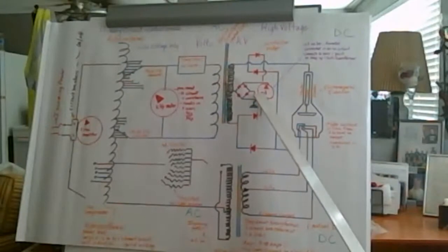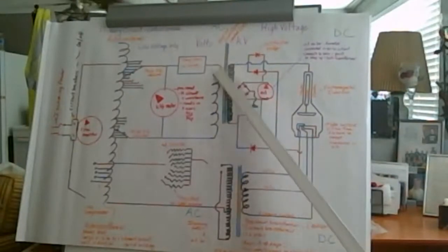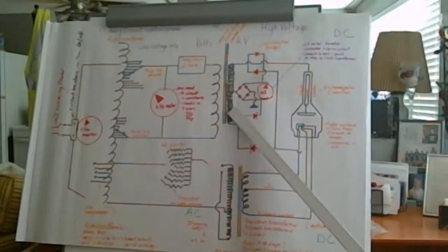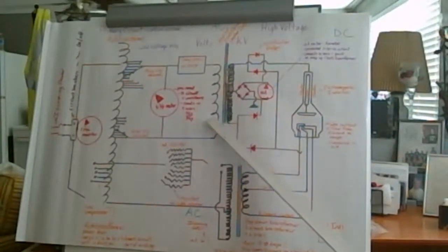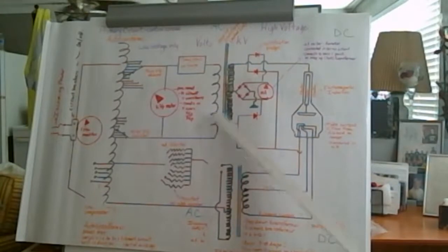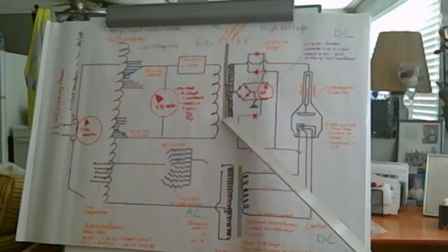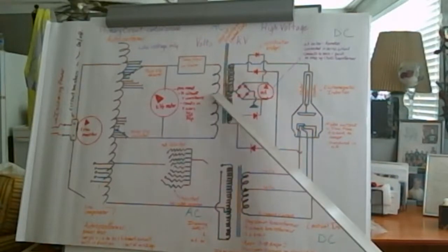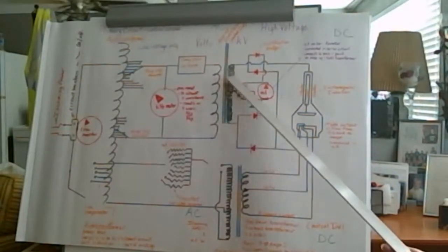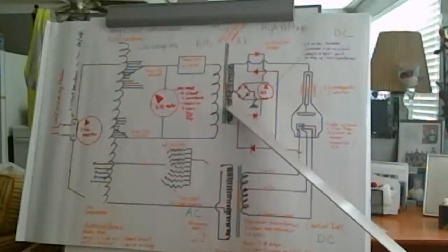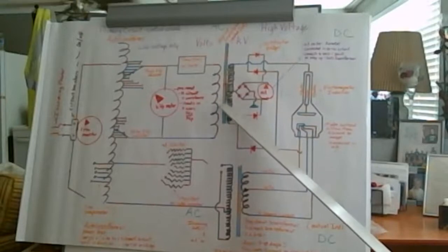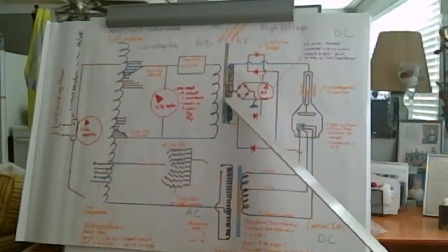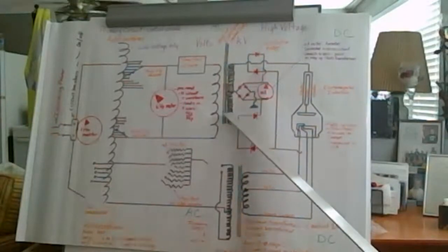Okay, your ammeter. All right, so this is your step up transformer. What happens is we go from volts on this side to kilovolts on this side. Our 220 incoming voltage can be varied on this side, and it will affect what we have on this side based on the turns ratio. So we're going to have kilovolts on this side.